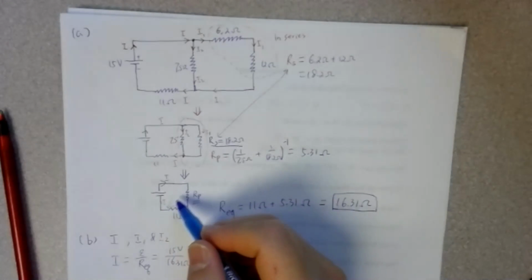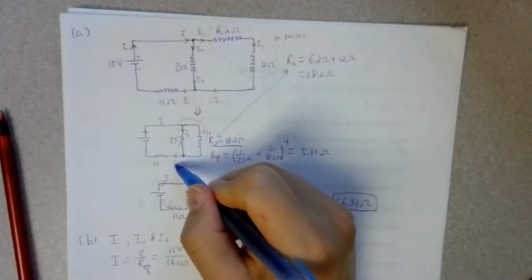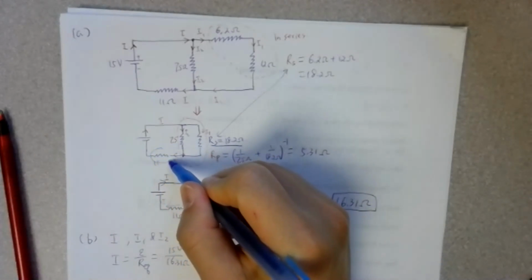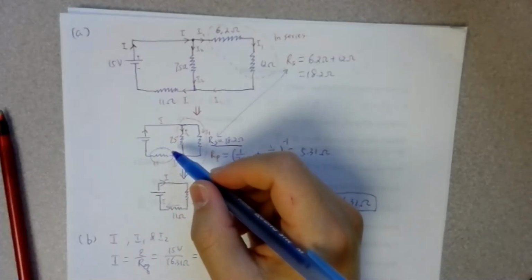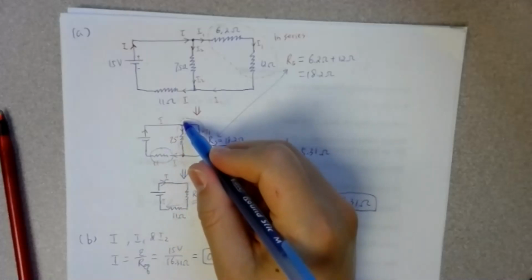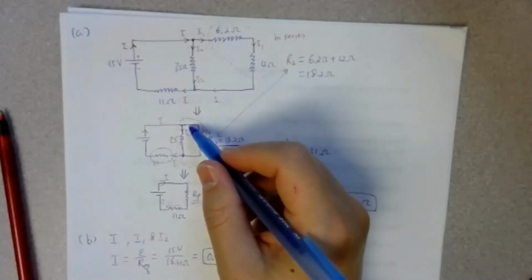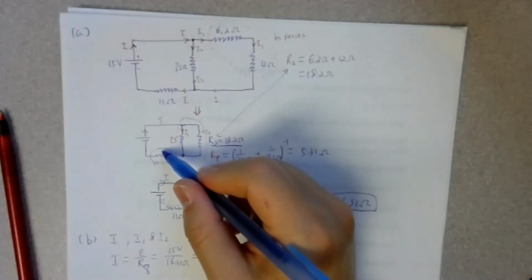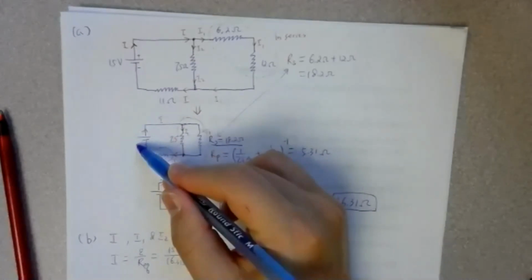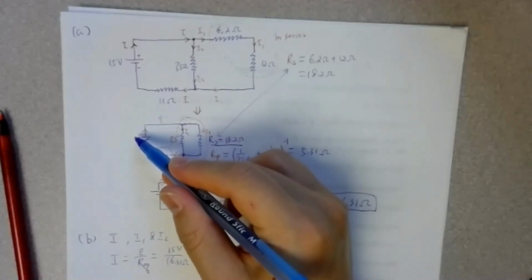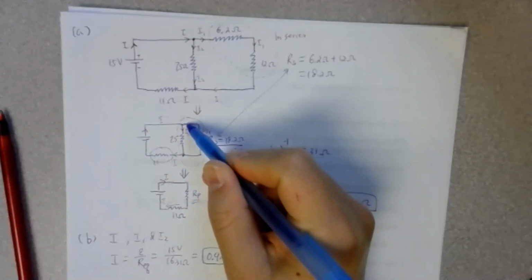Because you have this one already figured out, I think we have used this circuit, so we can look back at this one here. If I have this I already, I can figure out the voltage across this resistor. And then if I have the voltage across this, I should be able to figure out the voltage across this part of the circuit, because the voltage across here plus the voltage across here should be equal to the voltage supplied by the battery.